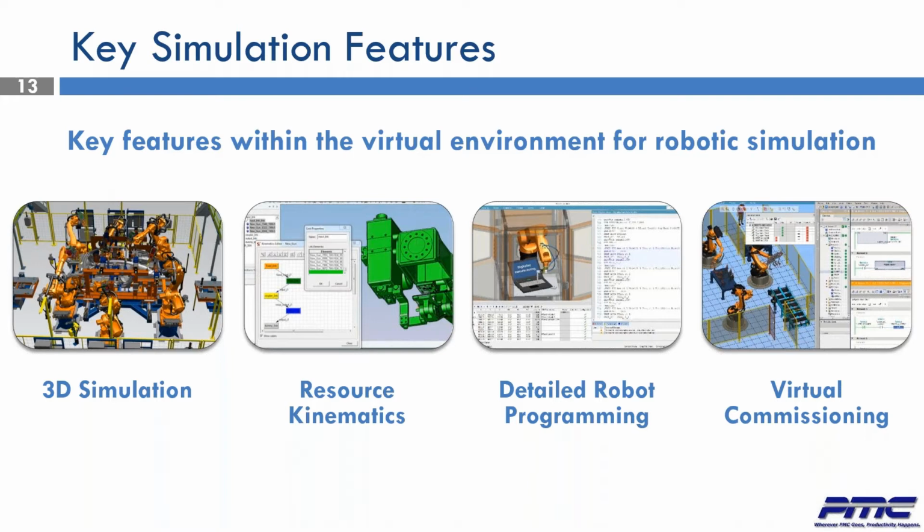That is, we can connect the virtual robot with a real robot controller. We can parameterize its trajectory with correct speeds, real types of movements, robot signals, release signals, and other parameters like gluing parameters or welding parameters. So it's the step of detailing the program before downloading and loading it into the real robot. And we can also work with virtual commissioning. It means that we can validate the robot logic and PLC logic within a controlled environment still in the planning phase. In this way, we don't affect or stop the real production environment.